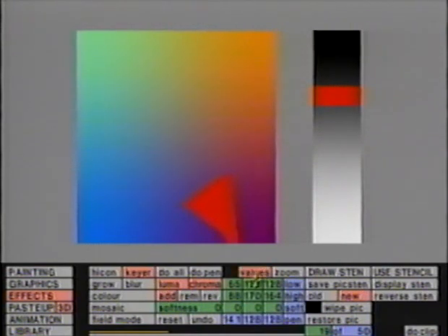The values box allows us to vary the key signal very precisely. The three vertical columns refer to Y, U and V, the luminance and colour difference components. The low and high boxes indicate the numeric keying range. With the pen in proximity, the values under the pen are displayed. By comparing the low and high values with the pen values, it can be seen which value needs adjusting to include the pen area.